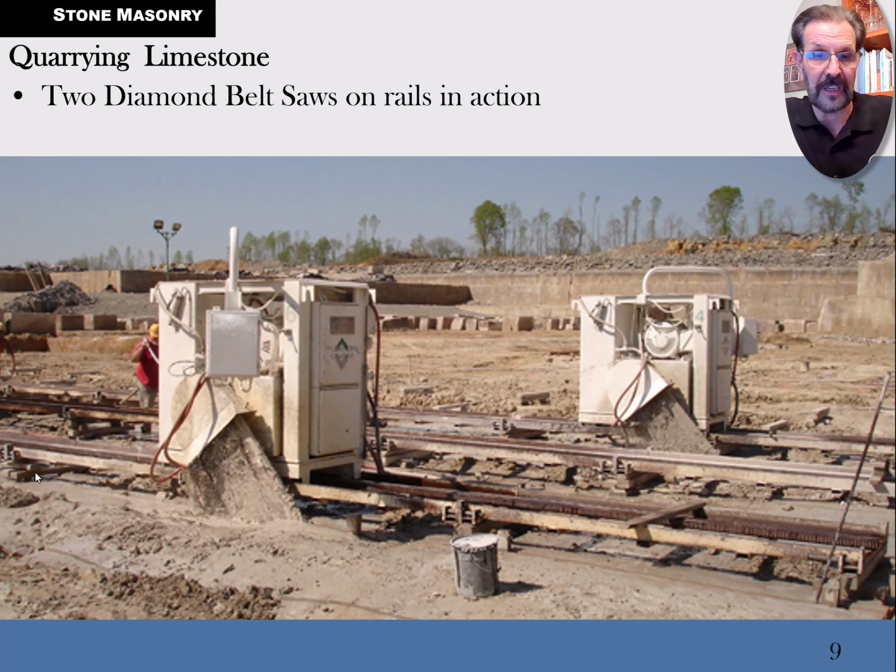These giant chainsaws, and that's basically what they are, are not like any chainsaw you ever dealt with or I've ever dealt with. It's cutting rock. And just about any blades that we use to cut through rock or concrete, we cool with water to keep them from wearing out and burning up. You see all this mud around there. They're literally keeping everything inundated in mud to keep it from overheating the blades.